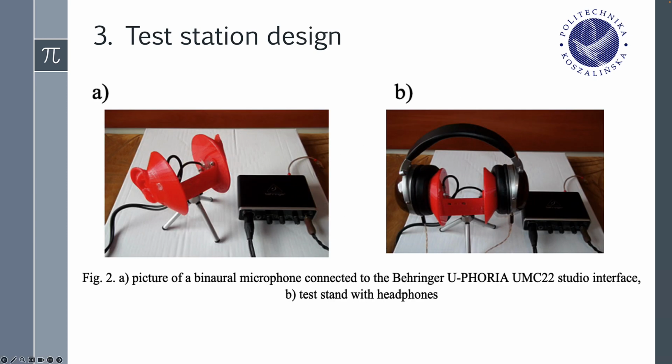The body for the microphone was the open binaural project shown below, made available for free under an open license by author Carlos Garcia Sora on github.com. The author has rendered the shape of the ear canal quite faithfully and provided space for the microphone capsule. The microphone capsule was fixed in the channel with silicone and then flooded for extra insulation on the pin side with polyamide glue, which is used for electronic circuits.